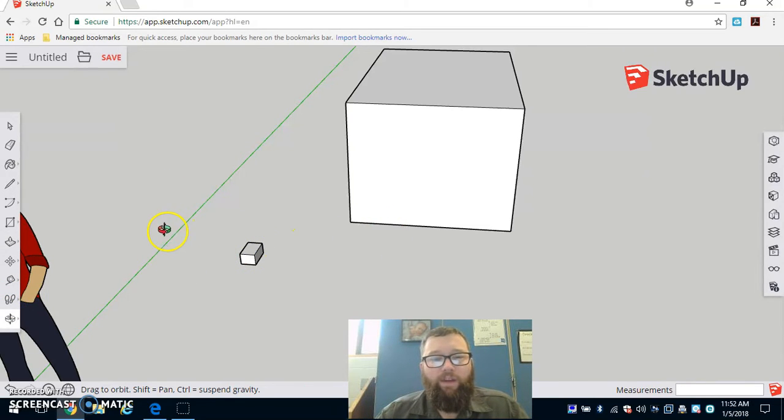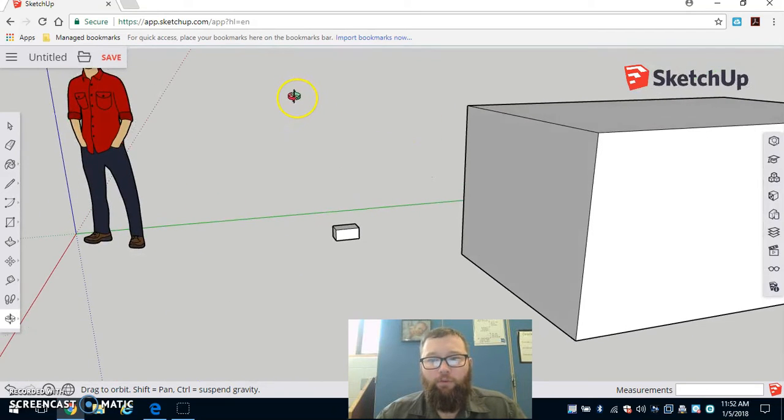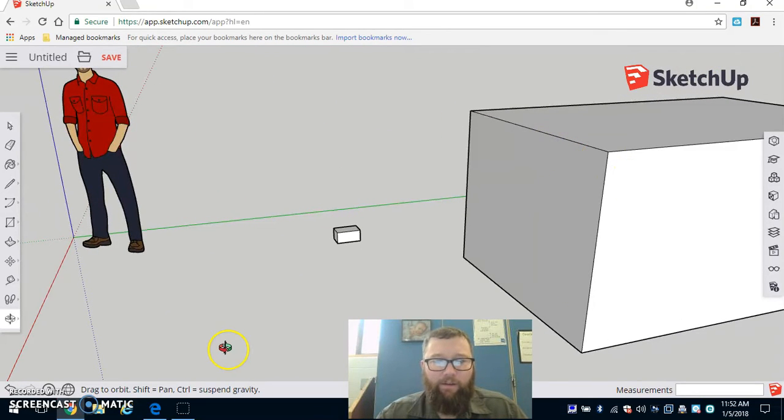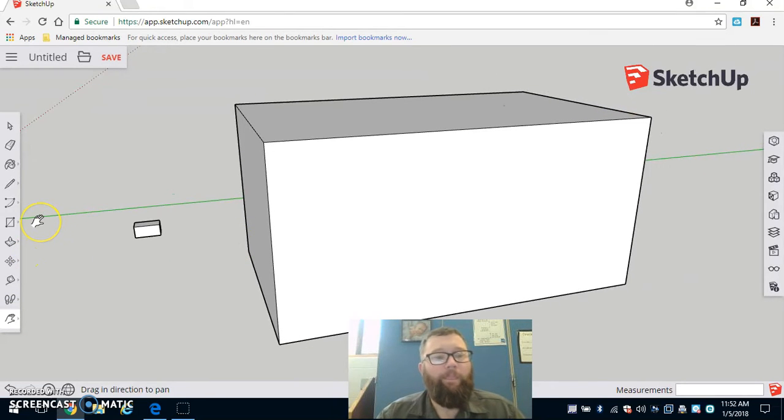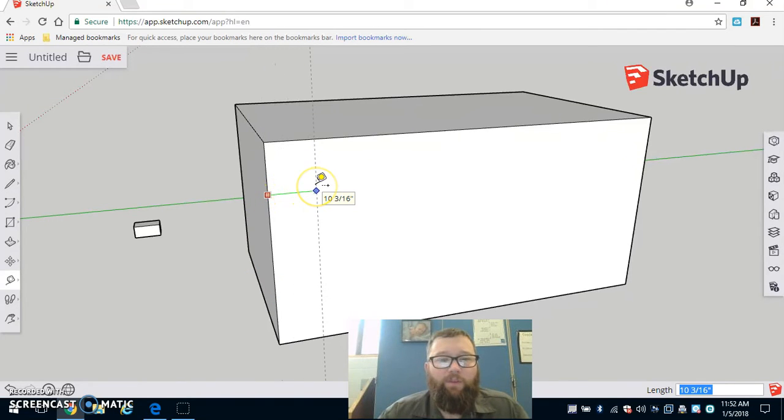One of the cool things about this software is it allows us to modify what we've already created. I'm going to use the hand tool, and I'm going to get a little bit further over. One of the tools that we can also use is the tape measure tool. So if I select that, I'm going to bring it over to the edge here, and I want a line that is parallel to this side, but I want it to be 1 foot away. So if I click and move the mouse away from there, I can again just type 1 apostrophe enter, and it creates a 1 foot line parallel to the side.